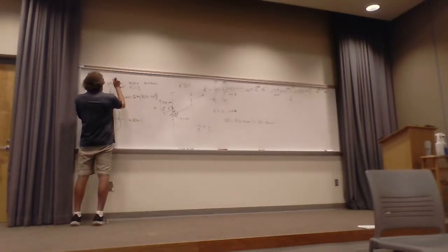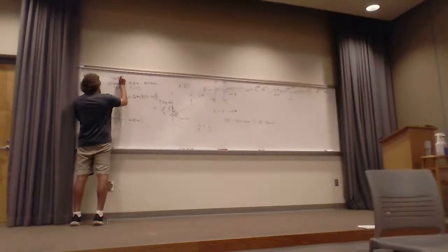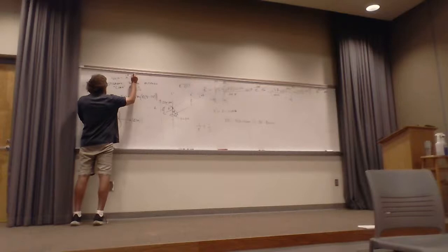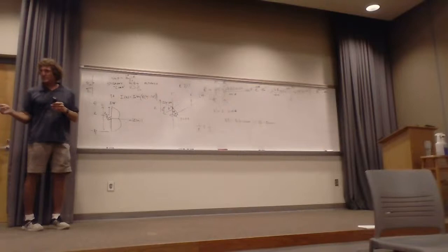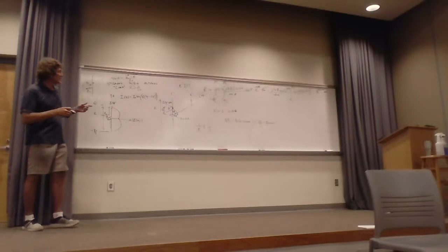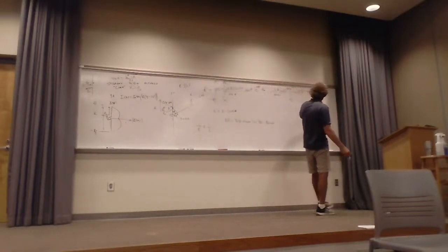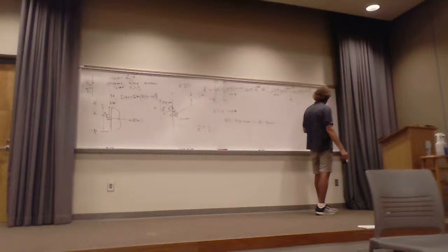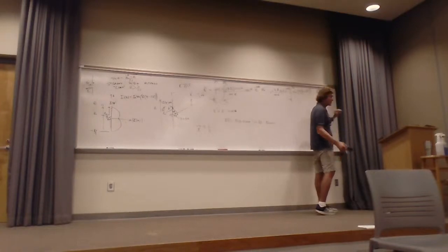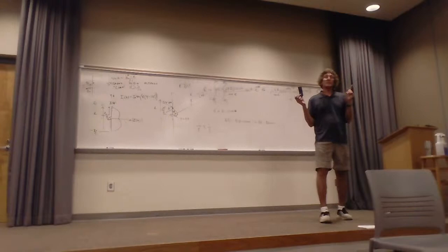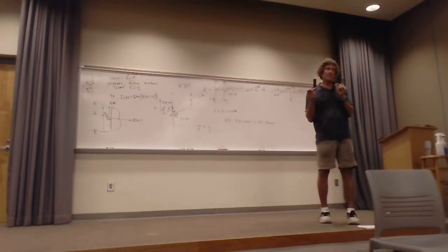You know how the sine of theta is equal to e to the j theta minus e to the minus j theta over 2j. You all remember that? That's Euler's identity, right? So you can take that sine and break it up as e to the j beta times L over 2 minus magnitude of z, minus e to the minus j beta quantity L over 2 minus magnitude of z, over 2j, and then multiply it by this. And then you collect the coefficients of the exponents, and you can do the integration.